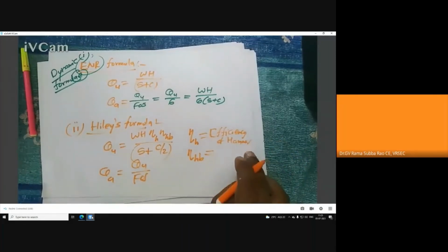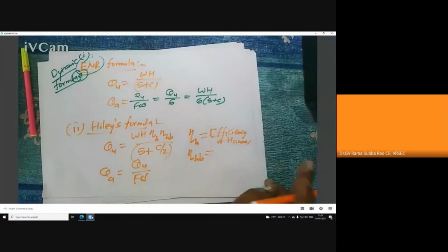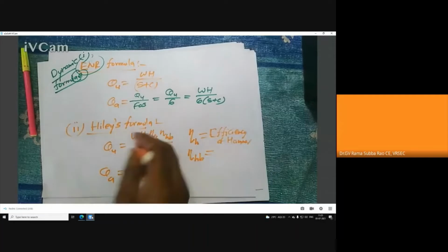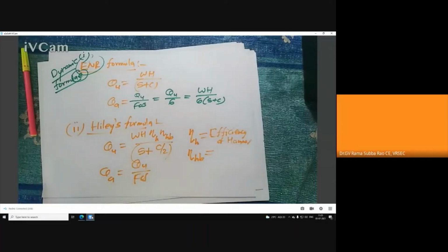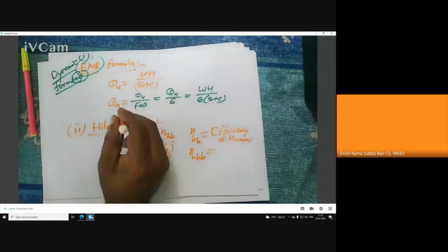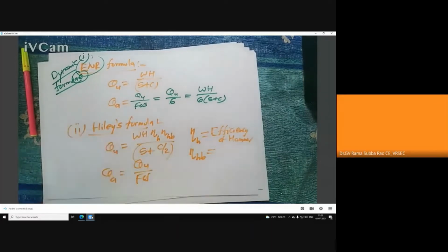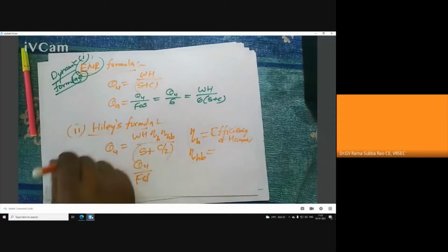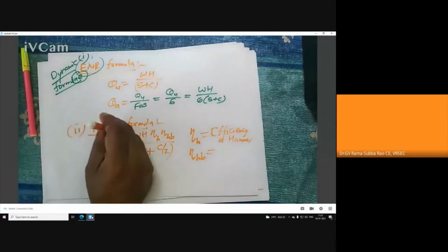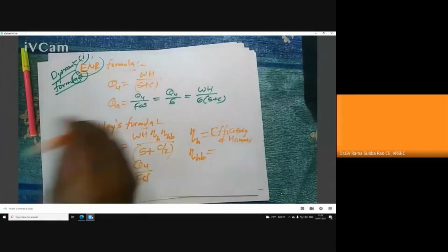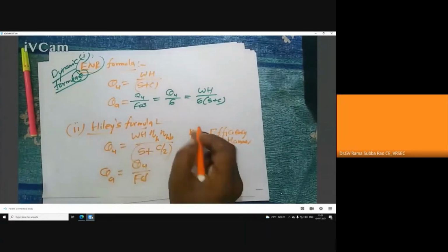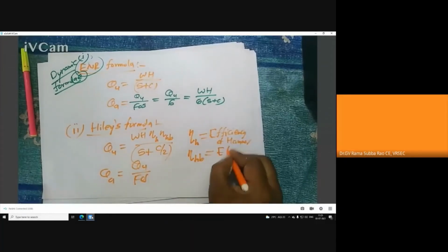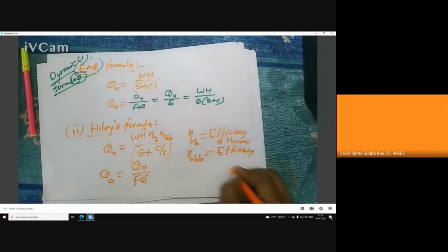So many times, we are trying to say our hammer is efficient, but we are not sure. I am repeatedly telling this during SPT also. When you are hitting the pile with this dynamic impact energy, there may be some energy loss. We are not sure every time we are maintaining the same height of fall. That's why we should consider efficiency of hammer and efficiency of hammer blow.